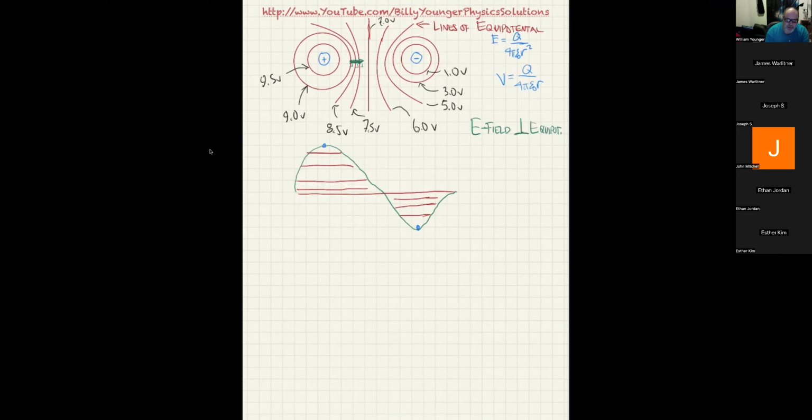Once you've done one whole line, sort of like one of the lines I've drawn around the positive thing, then you stop and try to draw a smooth line through all the points you found. Then you move the one that you left sitting still the whole time and put it on another part of the carbon paper. And then you find all the places that give you 0 current relative to that. That'll make a second red line. And you keep doing that until you get about 7 or 8 lines in between your shapes. And you then have the topo map basically.